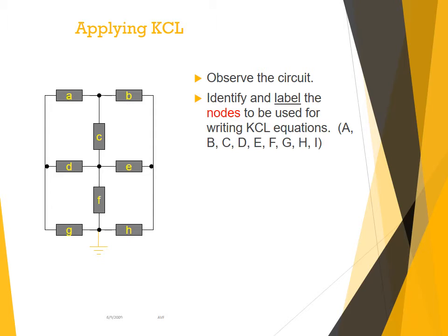What Kirchhoff's current law expresses is conservation of charge, and what it says is that the sum of all the currents going into a node is equal to 0. And so what we will learn today is how to use that law to solve for all the currents in your circuit, as long as you know other currents in your circuit.